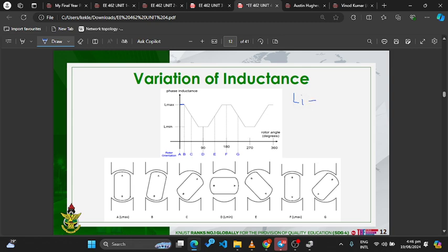That's flux linkage, right? There's a certain formula like we know Ni is equal to flux times reluctance. Okay, so I can make I the subject here. If I make I the subject here, it will be this times S divided by N. Right?